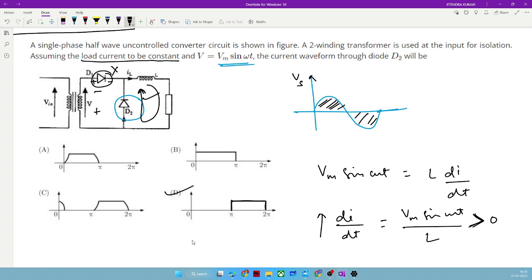So the concept behind that: this diode will freewheel its current through diode D2, whatever the load has consumed or inductor has stored energy during initial pi period, right? So it was a bit intuitive, and the role of freewheeling diode would have become a bit clearer, I guess. More about freewheeling diode we will see in the next topic, I guess.